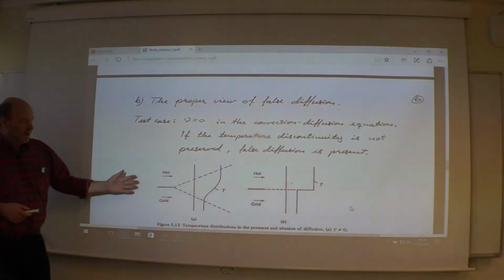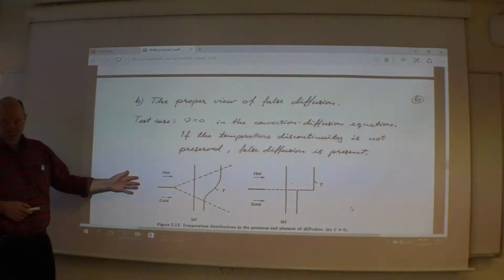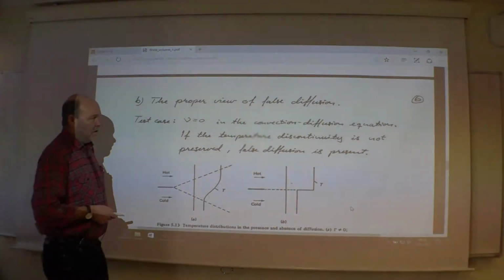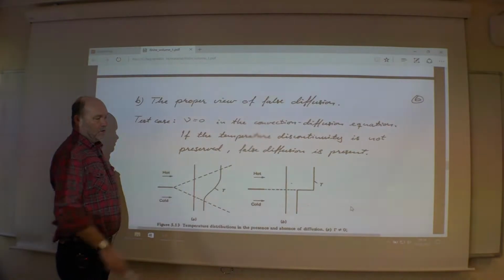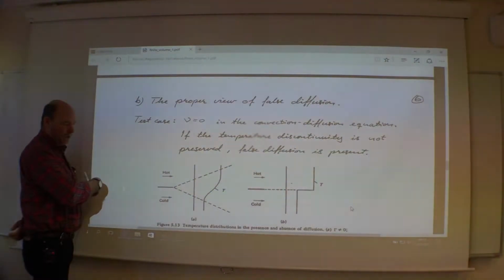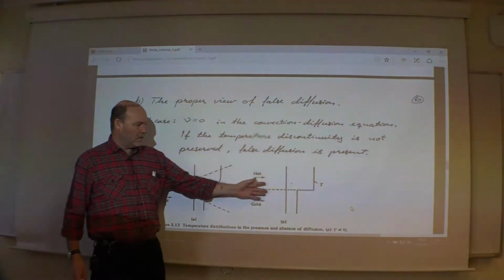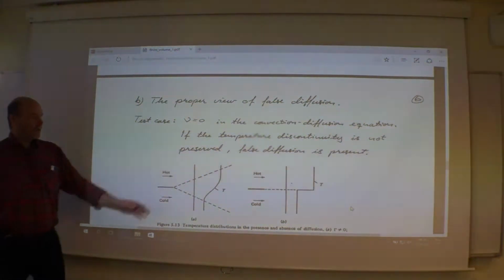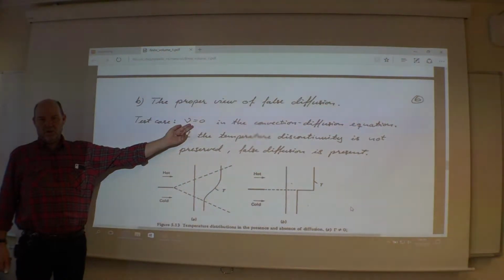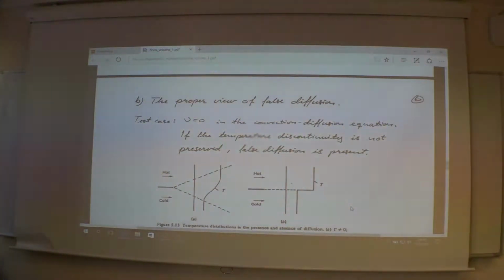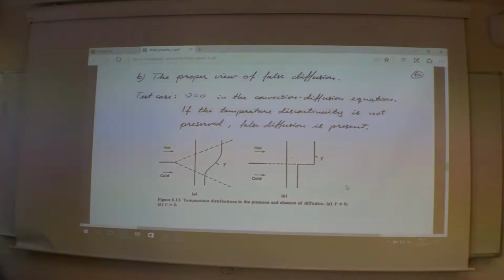And here, if you simulate this one, now with the first order upwind scheme, of course you get that. Because the first order upwind, with no double derivative, just picks the value to the left when the velocity is positive. So of course then you get the very correct solution. With the central scheme, it can't be done at all when you don't have any viscosity. It will be negative, it will just explode. That's actually not entirely true, but in general it is.